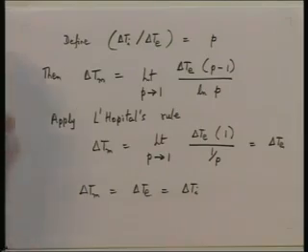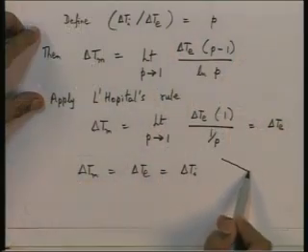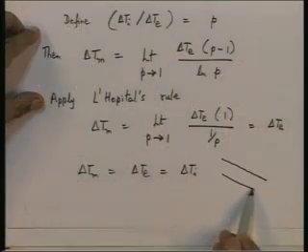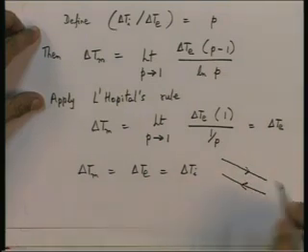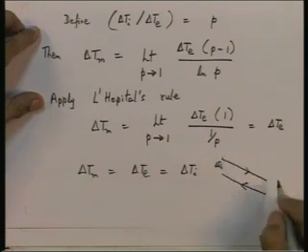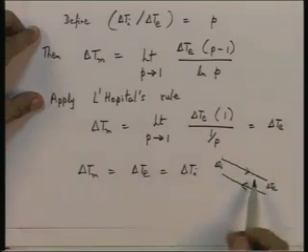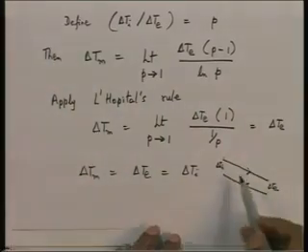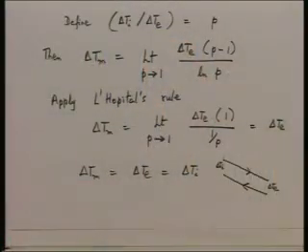And in fact, in this particular case, what really happens is the following. What we really get is the temperature profiles on the two sides are two parallel lines like this. This is on the hot side, this is on the cold side, this is delta Ti, that is Thi minus Tce, this is delta Te, which is The minus Tci. And if you have two parallel lines for the temperature profiles, it follows that delta Tm must be equal to delta Te, must be equal to delta Ti. That is really what we are getting.